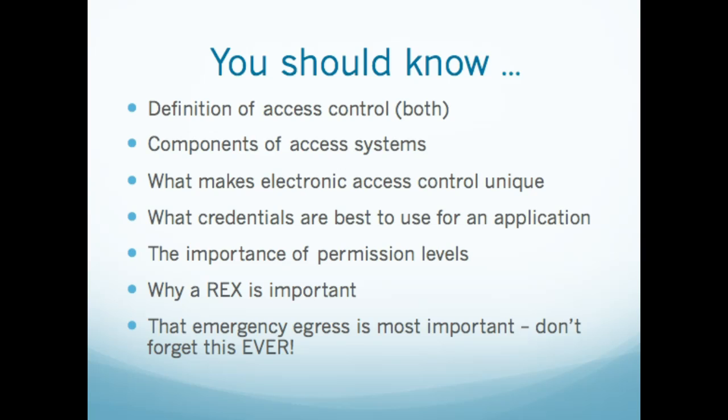You need to understand that when you get in, you have to have a way to get out. And if there's not a reader, if it's not required to read in and out, and you want to save that money, you have to have a way to disable the lock or open the door and to tell the system somebody on the inside who's legally here is getting out, open the door for them. That's where the REX device comes in.